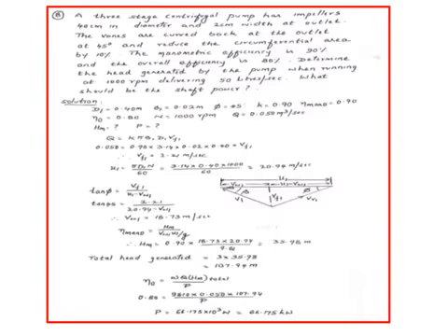So this is a problem where we have a three-stage centrifugal pump. Three stages means there are three impellers mounted on the same shaft. Whatever water flows from one impeller is driven with some particular head, then goes through connecting passages to the second impeller. Again, it will be thrown with increased head. Like this, when it comes out of the third impeller, it will again be of more increased head.